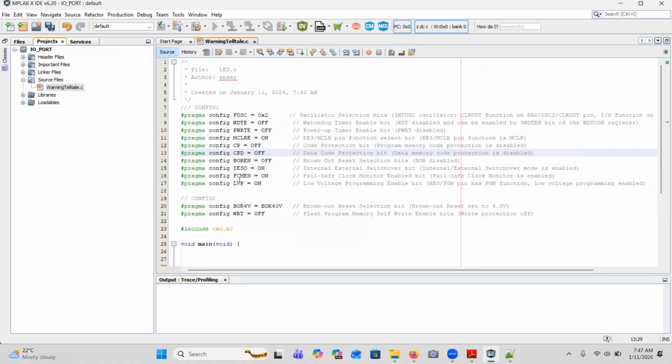That binary may work or may not work, because these are the board related parameters that we have to define. If we don't define these parameters according to our board and controller, they are undefined. If they are undefined, the output is not predictable.